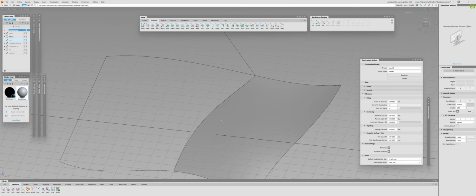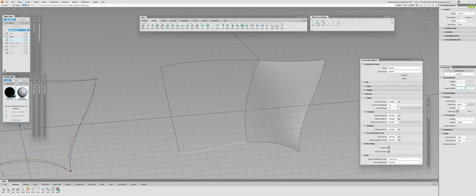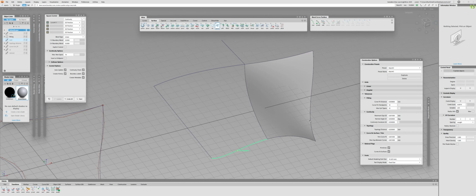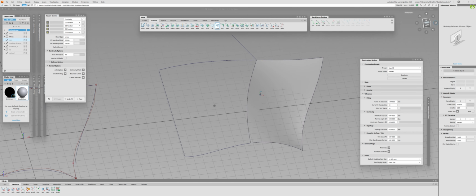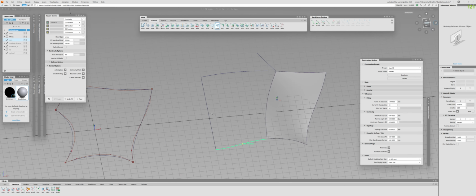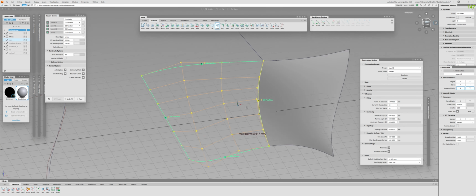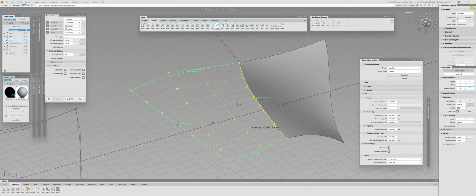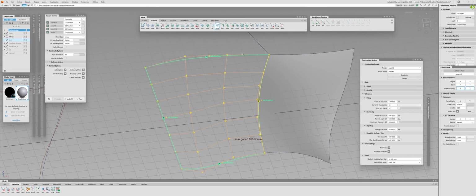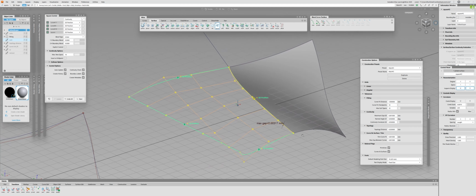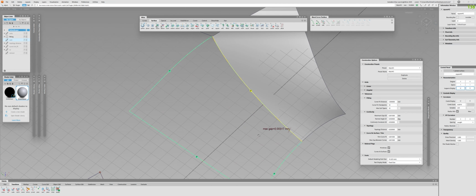Now, this is only one of the examples. Now let me create a square using this dirty edge. So I will use the square tool. I'm not using explicit control and am basically relying on Alias. And once again, let me just loosen the tolerance, and then create the surface. Now, as you may predict, the surface is really clean. The tolerance is high, so the surface is really clean, but it's not positional again. Once again, we have a small deviation in the position.